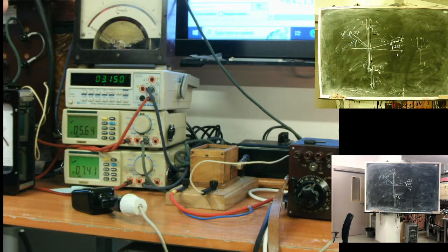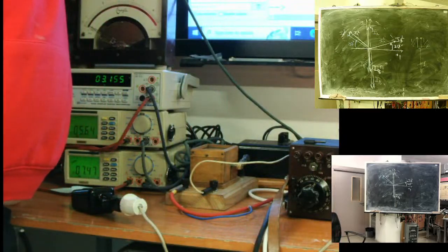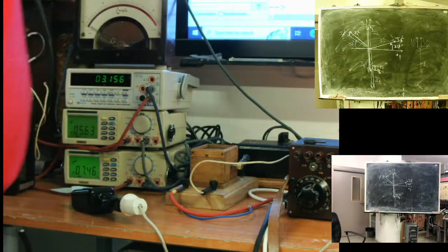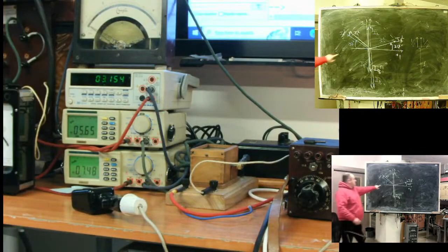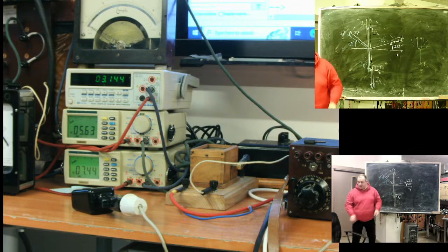See what point? The asynchronous machine takes the negative sequence to itself. It's a small resistance for negative sequence. Now what will be on the primary side? On the primary side, we should see 2.8, 6.61, 5.15. See, no longer too small and too large, because this blue part is much smaller. It's, let's say, sunk by the asynchronous machine.